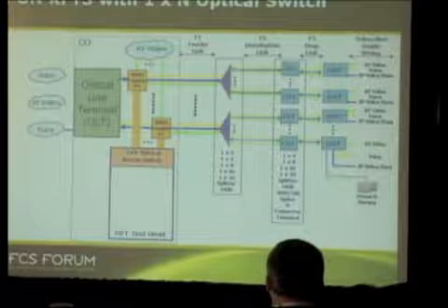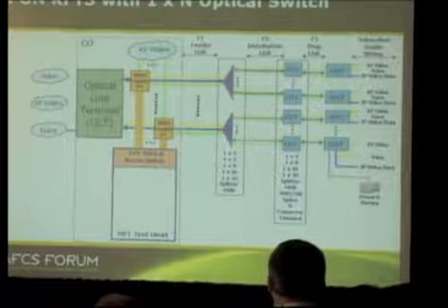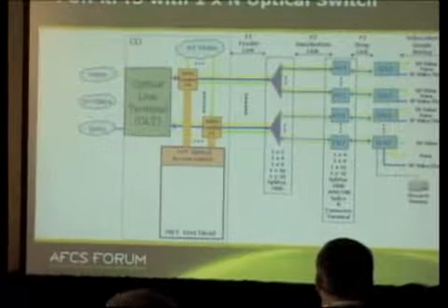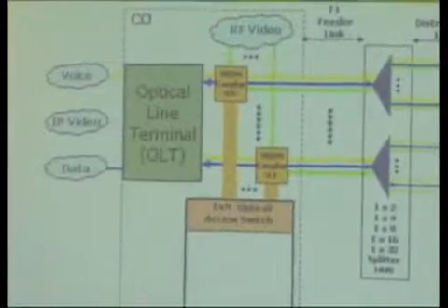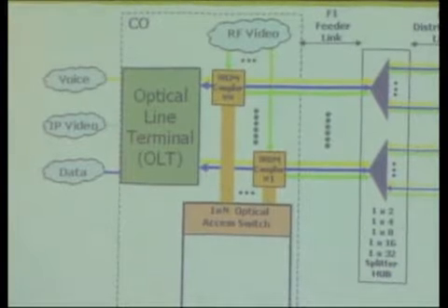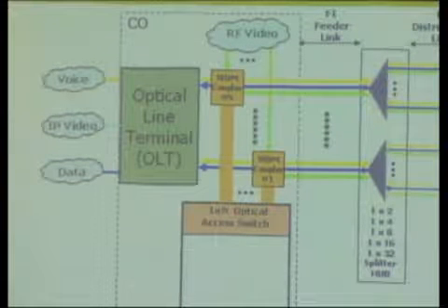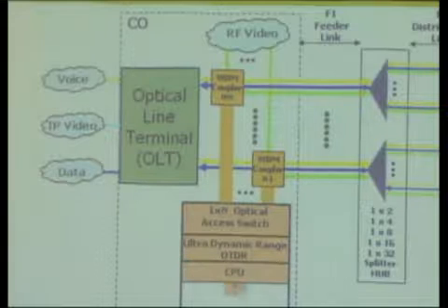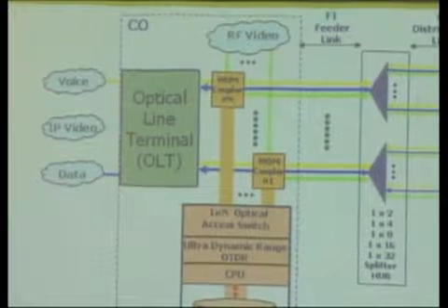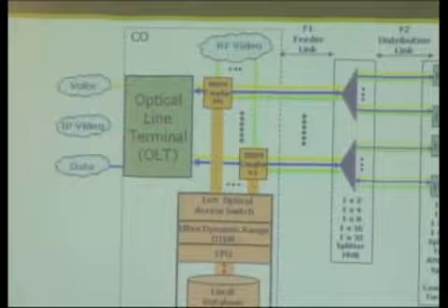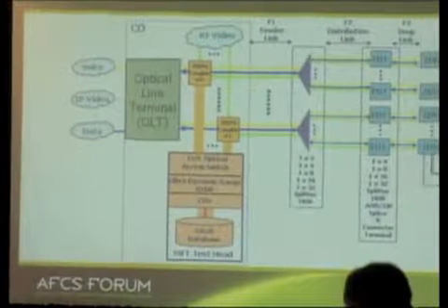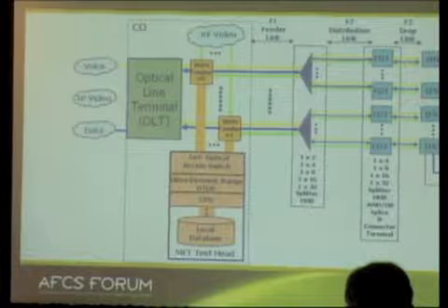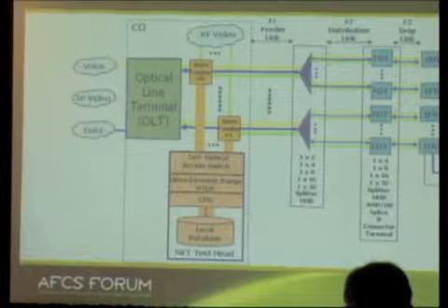So in a remote fiber test system for PON, not much different from what Troy was talking about, we go into a WDM. Either we share a WDM where you have RF or you put one in for testing, because, again, we're going to be using a wavelength that's non-intrusive in this case. We have an OTDR with extreme dynamic range. We're not going far distance, but we have a lot of loss.